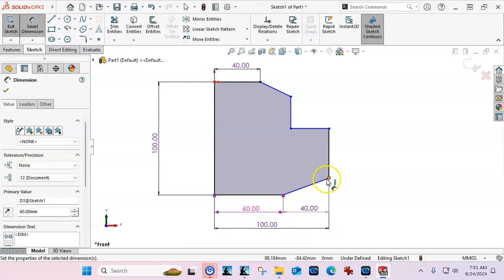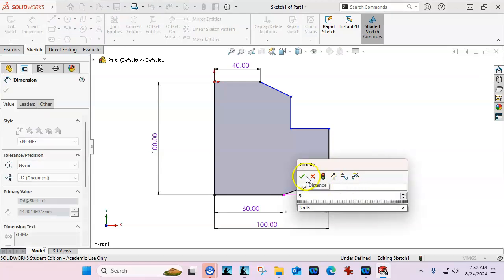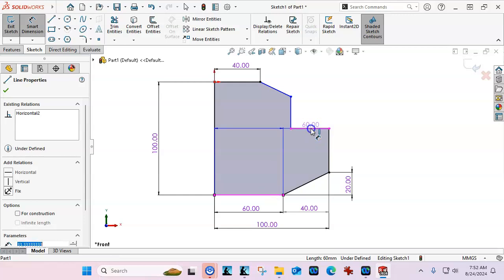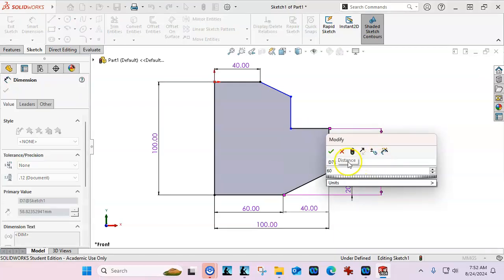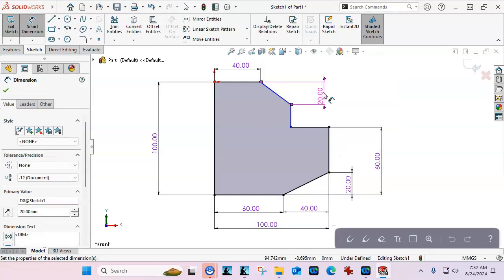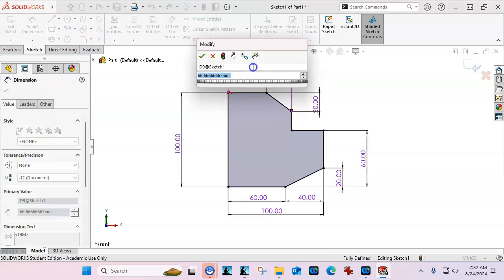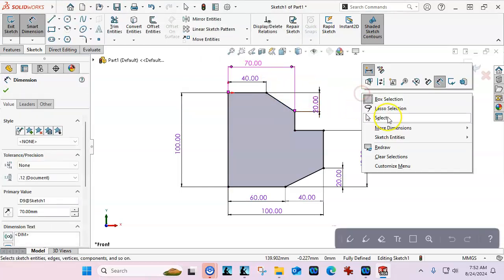All right, so unless you want it to act as a kind of reference, the driven dimension doesn't do a whole lot for you. So I'm going to stay with the object, pull off to the side for vertical, and go to 20 millimeters. Between the two objects is 60. So my vertical, go back to an object, and try different things. Find out what works. One of the things with the points, depending on how you're managing geometry, is that points also allow for an orbit, which can be a little bit strange.